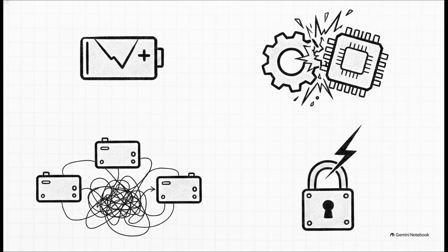It's wild. Third, communication database drift. This is where tiny version differences between the vehicle control unit, battery management system, and power control system cause data to shift around, turning your safe torque limits into completely random, dangerous commands. And finally, secure boot failures. Think cosmic rays randomly flipping a bit in memory, or unauthorized firmware bypassing the initial safety checks entirely.